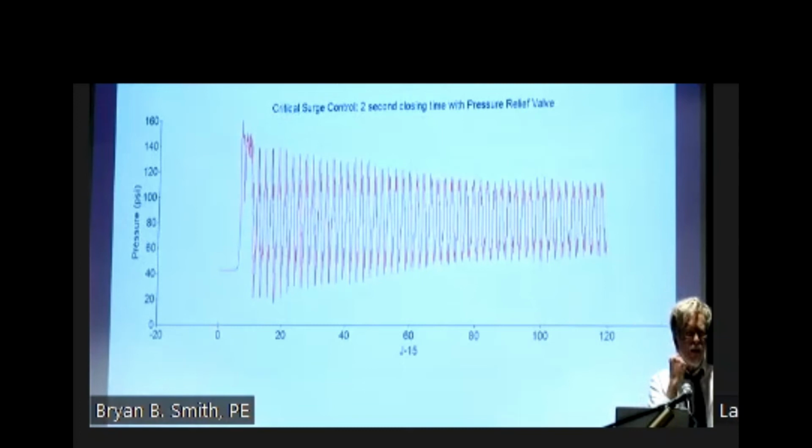And then the negative wave goes out, because remember, it's traveling back and forth in my piping system. It's like, relief high pressure wave. And guess what that wave did? It went back out negative. It's like my relief valve was like, guess I can close now, right? You know, the high pressure wave left. The valve goes closed. I'm good.